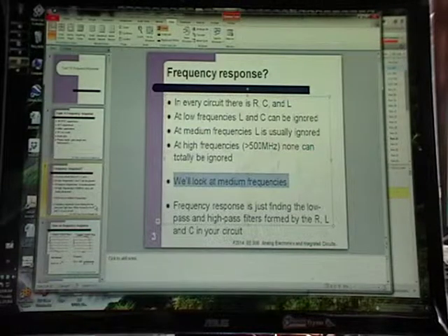Because our equipment isn't good enough to see the actual poles and zeros, we're going to add capacitors to our designs in lab. The actual R's and C's give us a pole and zero so high that we can't observe them, because our equipment can't see that high a frequency.